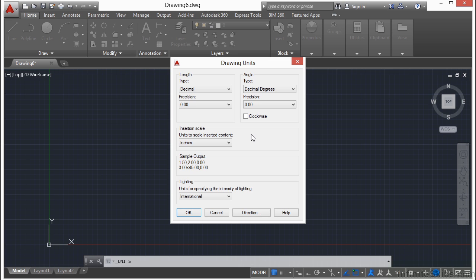It'll say it is 12 feet, 0.0000 inches, or whatever that case may be. One of the problems that you have to deal with in AutoCAD is that it is way too precise for a lot of our applications. You can draw much more precisely in AutoCAD than you could ever build for a lot of different things. So keep that in mind, and just because you can draw something in AutoCAD, that doesn't mean that it can be built that way.